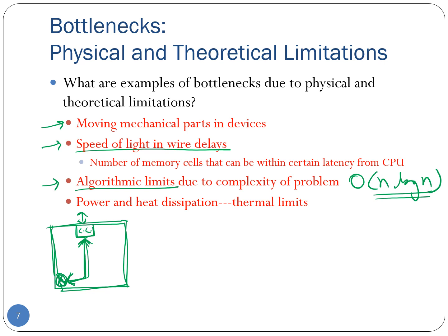And finally, there are also thermal limitations that dictate the speed of computations on chips. So for instance, for simplicity, let's assume that in every clock cycle we can finish one instruction. Okay, so let's say this is the clock frequency and this is the cycle time. So if our frequency is 1 gigahertz, the cycle time would be 1 nanosecond, which means every nanosecond we can finish one instruction. If we increase the frequency to, let's say, 2 gigahertz, we can finish an instruction every 0.5 nanosecond, and so